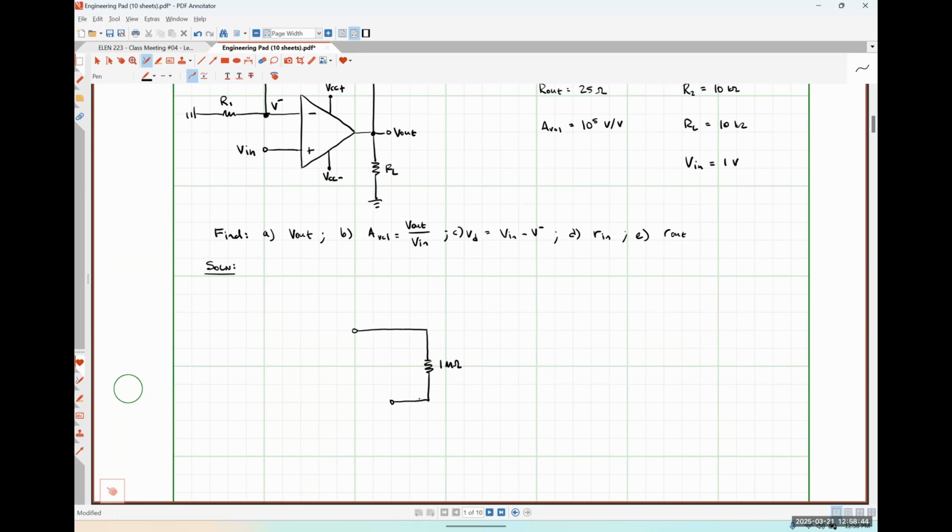And I'm going to choose to put the positive polarity or the non-inverting terminal on bottom, just going to make the feedback easier to draw. So this node is going to be V plus, and this node will be V minus. That's making my differential voltage here with positive polarity on bottom, because the positive polarity terminal of VD is always at the non-inverting input node.